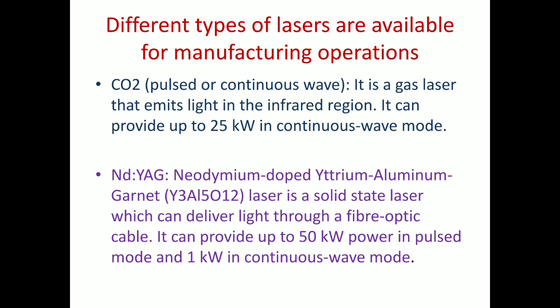So generally this laser should be used where we want to do discrete manufacturing, that is drilling at different spots on a sheet. There it can be used, not for cutting purposes. So drilling purposes or certain other discrete manufacturing can be done with the help of Nd:YAG laser.